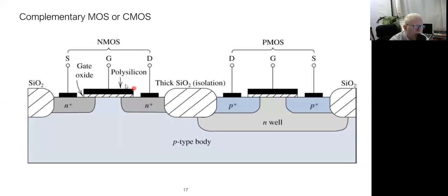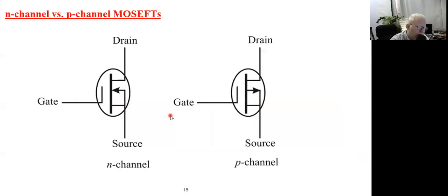So for example, in the case of the N channel MOSFET, we need to have a positive gate voltage. However, in the P channel, we apply a negative gate voltage in order to accumulate holes here, or to invert this region to be P type. So it's typically the same concept with a different polarity. Now, this is the end of part number one. It's related to refreshing our knowledge of the MOSFET and also going through the IV characteristic curves.